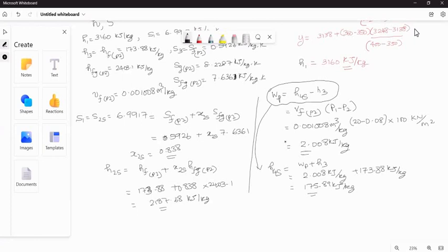So turbine work, now we are moving to the turbine work. Now you can ask me, so why H4S? The purpose of having the H4S, now you will see again turbine work, WT, that is the work output, H1 minus H2S, right? Actually these values you already have. Now 3160 earlier you had anyway. This is 59.3. It's okay.